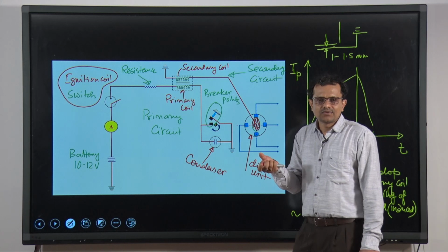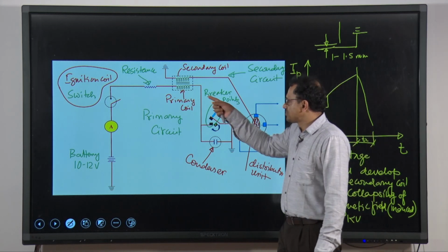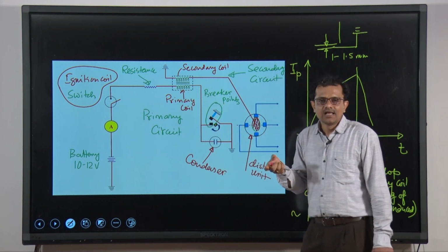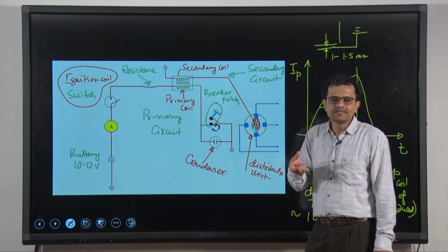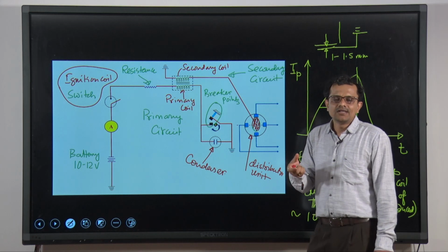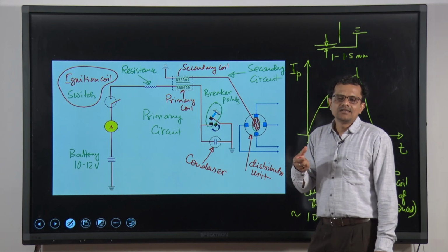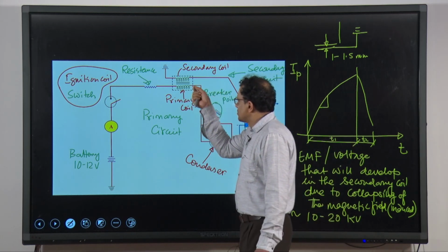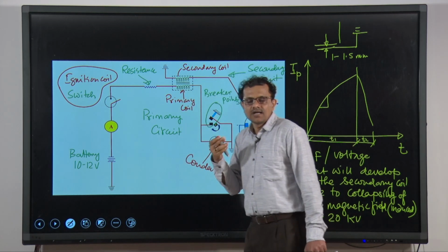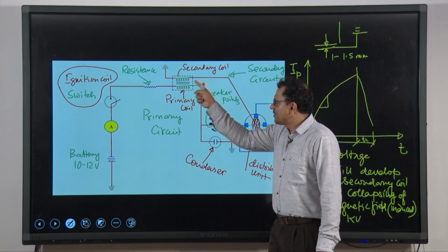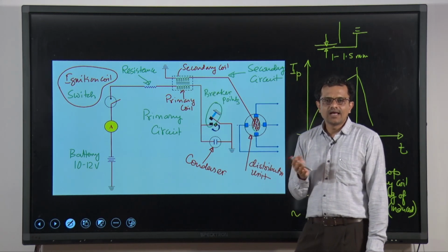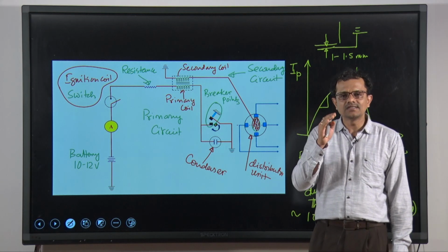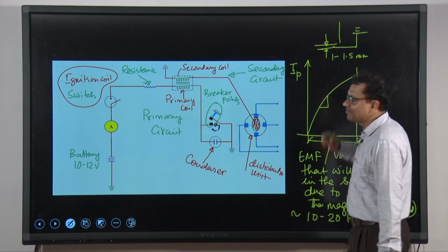So, these two processes, building up the current flowing through the primary circuit as well as collapsing the current, will be delayed, which will produce some problems to develop high voltage in the secondary coil, and if the voltage is not proper, then it is not possible to break the resistance in the small gap which is needed.